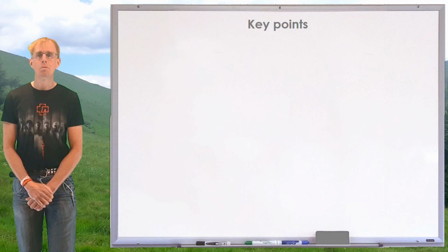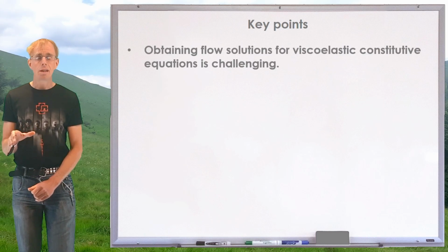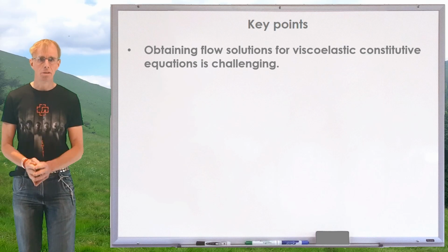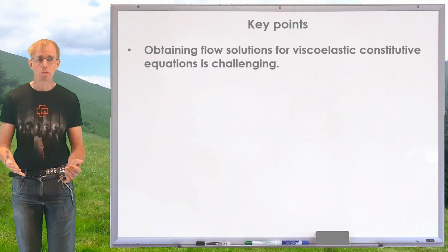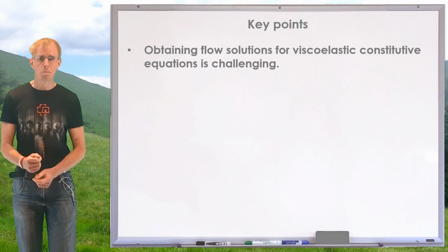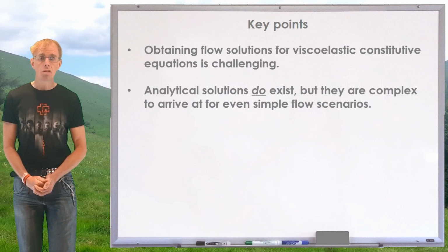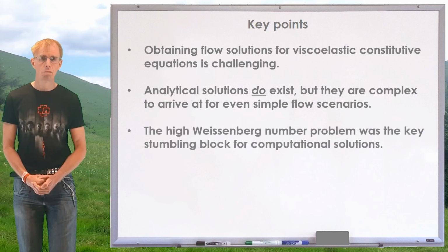Okay, so let's wrap up with a few key points. The key point of this final part of Lesson 5 is to state that, look, viscoelastic flow modelling is a challenging pastime. It is not de rigueur yet still. Newtonian CFD certainly is, even turbulent flow Newtonian CFD is. Polymeric CFD is hard, and it will take time, and it will take investment of either money or time. Analytical solutions to flow models exist, they are complex to arrive at even with simple flow scenarios.